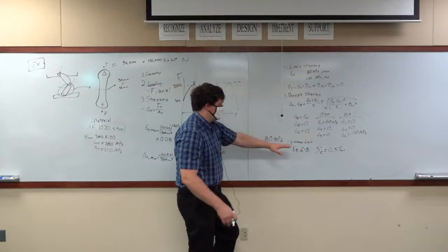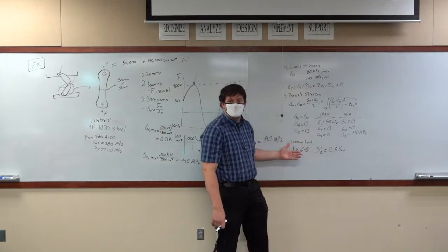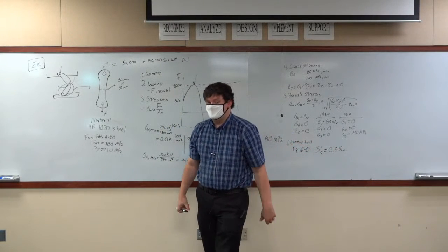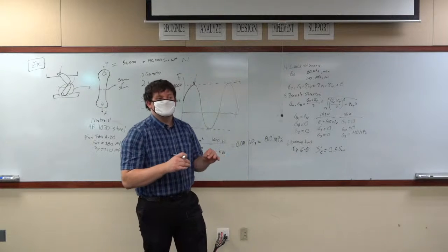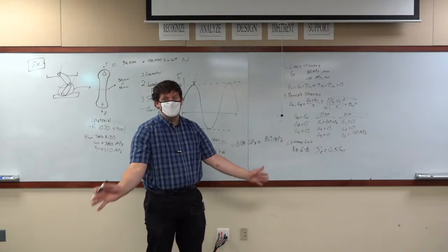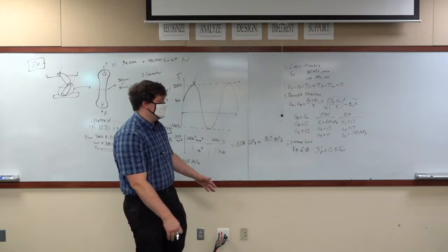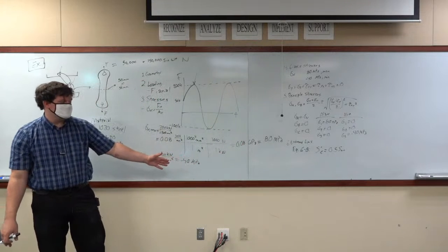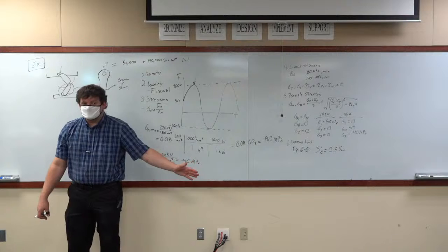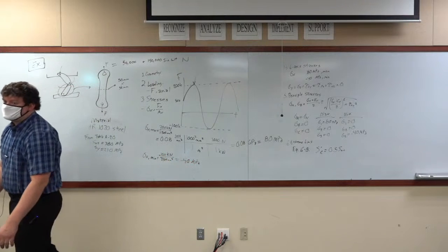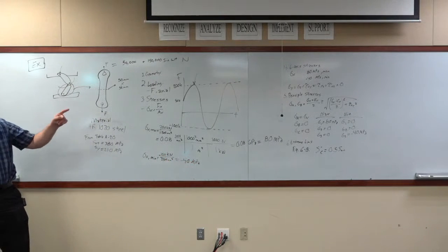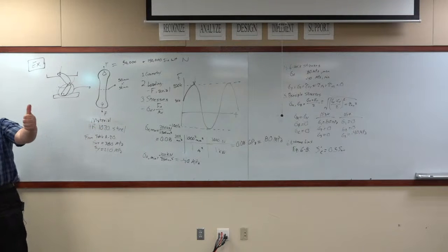Then you don't need this at all. You just plug in the straight value, you're good. If that's the case, awesome. Move forward, we're done. You can do your own tests to find what the endurance limit is. You can build your own SN curve for your components. And when you do, you find the endurance limit and you're good.